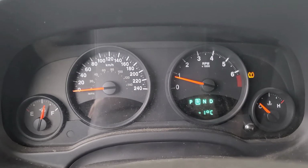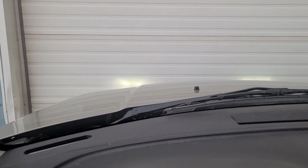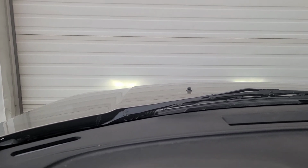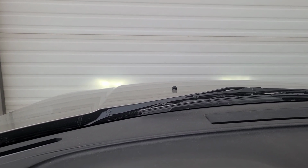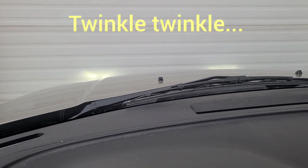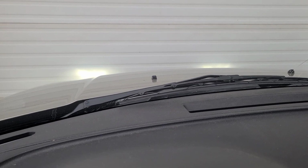So that got all the warning lights off except for the TPMS light because it's missing TPMS sensors. But you will notice, if you look at these daytime running lights here, you can see them actually flickering. And that's because the TIPM duty cycles the conventional headlights at about a 60% duty cycle. I'm not sure what the frequency is, but regardless, an LED light will respond to that frequency, and so the lights will be flickering on daytime running light mode. Of course, if you put the headlights on normal, they're on 100%, so they don't flicker.